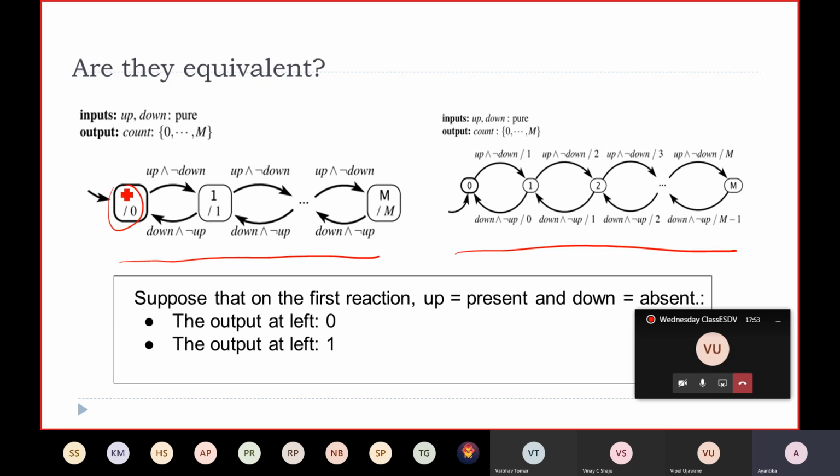So here, if you consider any state, 0, 1, these are my output values. These are my count values that will be displayed outside the counter, I mean, outside the parking lot display. But when I am considering this Mealy approach, I am considering based on this transition. So for the same state, if I'm going by this Moore convention, my output in this case is 0. If I'm going by Mealy convention, my output is 1.